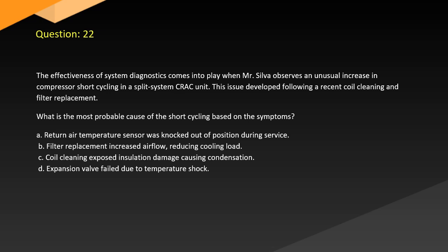A. Return air temperature sensor was knocked out of position during service. B. Filter replacement increased airflow, reducing cooling load. C. Coil cleaning exposed insulation damage causing condensation. D. Expansion valve failed due to temperature shock.